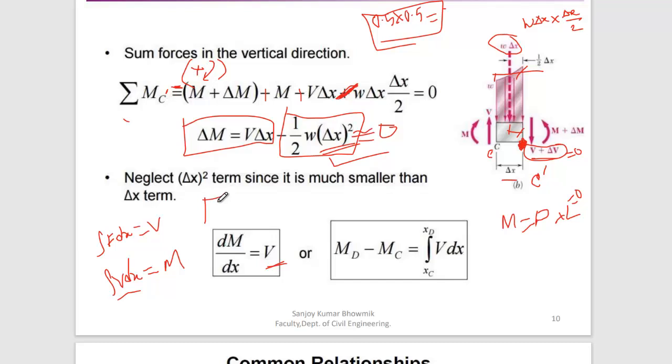From the force diagram, we need to calculate the SFD, the shear force diagram, and then the BMD. If we integrate the force diagram we get the SFD, and once we know the SFD, we can get the BMD.